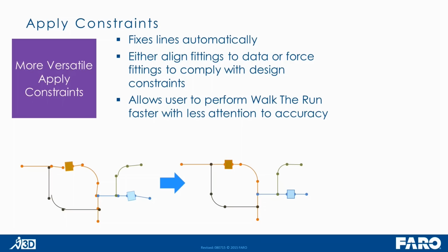We have a number of ways to do it, just reading the data that we have, and then we also have two methods. And I want to explain just briefly the difference between the two methods because they both have their needs. One is going to be a perfect version of the fittings for your design products. That means all of your 90s are going to be perfectly 90. Center to end lengths won't change, angles won't change, and then you're going to have the times where you need all your center lines to line up, but you need the fittings to actually show their true angles. That's probably most prevalent with cutback and routing elbows, and we actually have a really good way to address that as well.